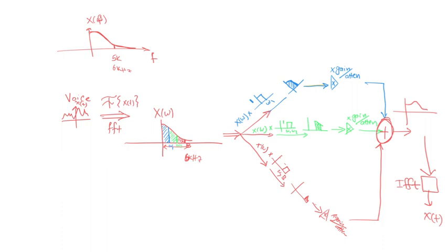And then the outcomes from those are going to go through some amplifier circuit with a controllable gain through a potentiometer or whatever, right? And then after that, you need to combine those three voltage signals. They are voltage signals. So you just need to add them one after the other, cascade the voltages, take the highest and the lowest, whatever. You'll see how to do it in the circuit itself, right? And then that final added voice, you just take it to the speaker.